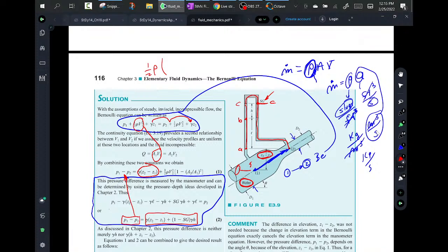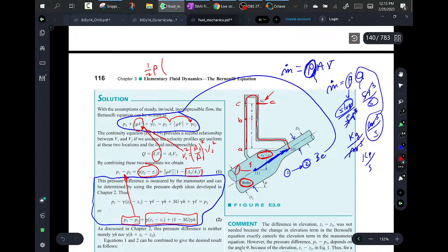Well, what is this? Okay, so it's A. Let me see if I can write this with the space I've got. V2 equals A2 over A1 times V1. So he injects this into here, and that's why, because you have to square this. If you're going to square it, the V1 squared can go back in here. So you will get V2 squared, 1 minus the area ratio squared. That's what the A1 is.